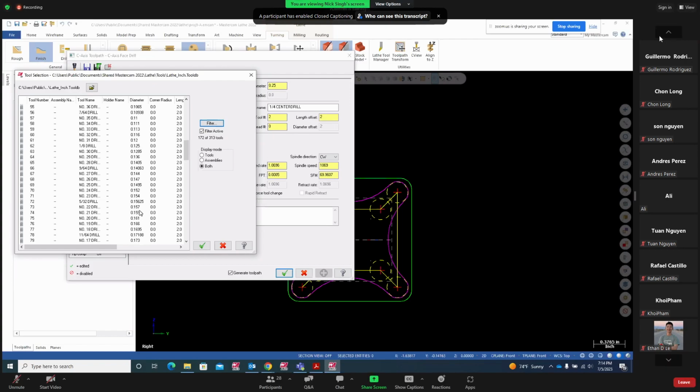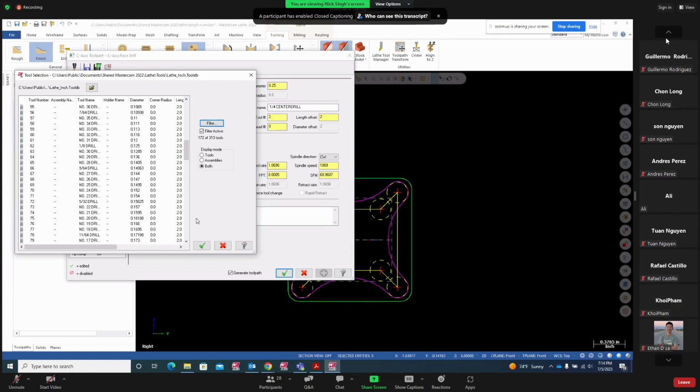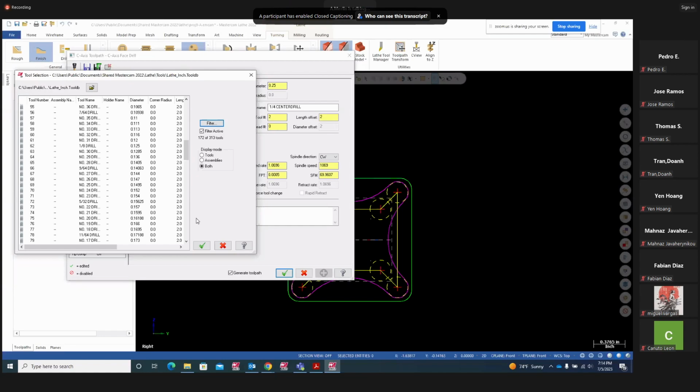Hey, sir, one question. Yes. Is the C-axis drill rotating the spindle in doing it, or is the drill working towards the position? The drill is rotating. The spindle is constant, only indexing to that degree. I'll just show you the program. The spindle is going to index. Your live tooling is turning on at 2000 whatever RPM, and it's going to drill that. It's controlled with your X-axis and C-axis. The main spindle is constant. Your live tooling is turned on. All right. Thank you, sir.